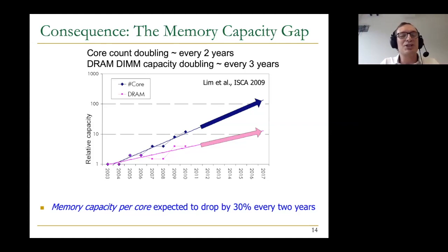In fact, there were trends in multi-core. Initially, when multi-core was introduced, people were actually excited about putting many, many cores on chip. Then they reduced the number of cores they started putting on chip, because they quickly figured out that these cores are bottlenecked by memory. What they did was they started putting more cache onto the chip so that at least they would alleviate some of the memory gap with an easy solution. Putting more cache is clearly an easy solution. We know how to do that, right? I mean, it's a patching solution.